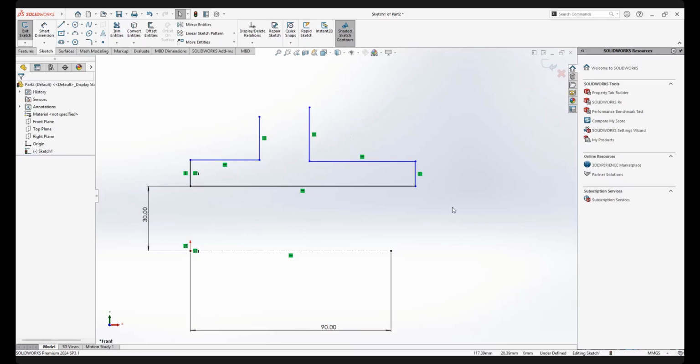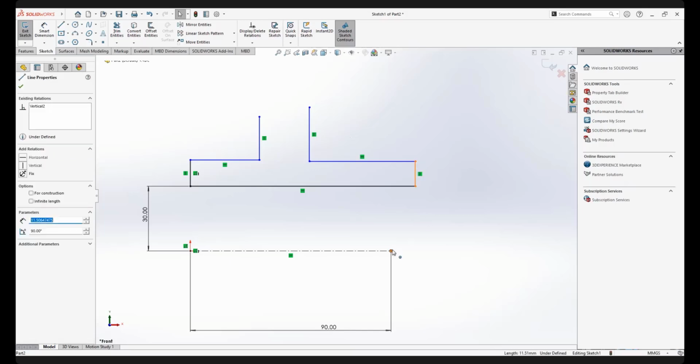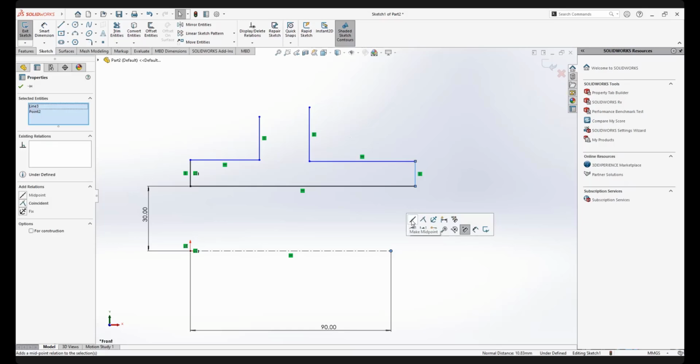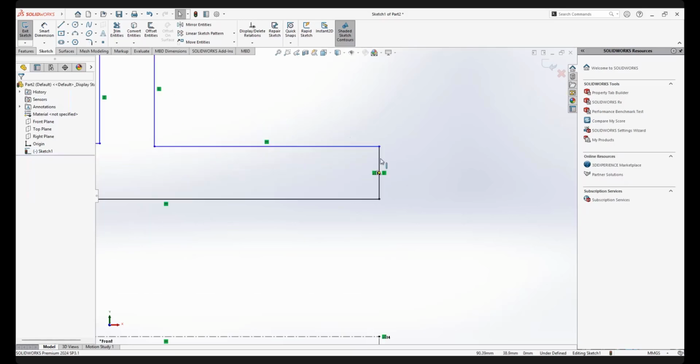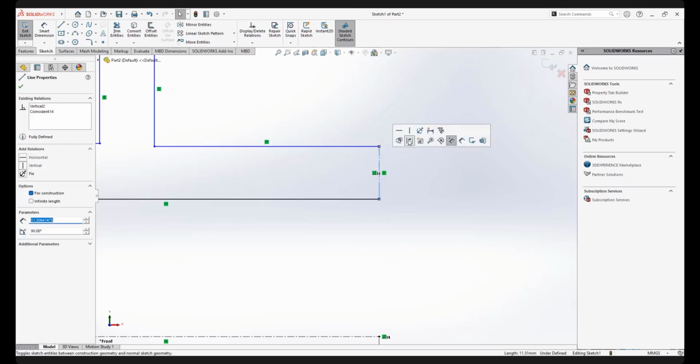Coincident. Yeah, you are right. This line, hold on my control key, select this dot. We go not midpoint. Midpoint is a middle point. The second one, coincident. You can also select it in the setting on the left, coincident. Can you see it become black? Black means that's good, right? We cannot move it. It is already fixed, okay. This one I suddenly set to center line.